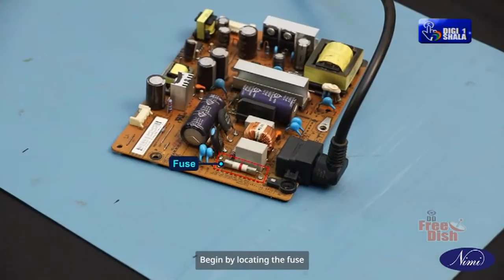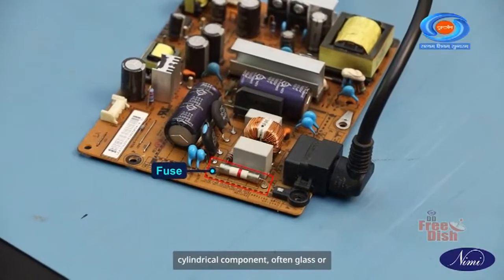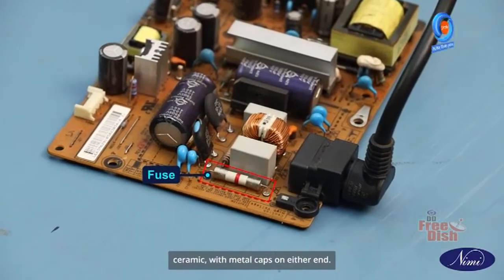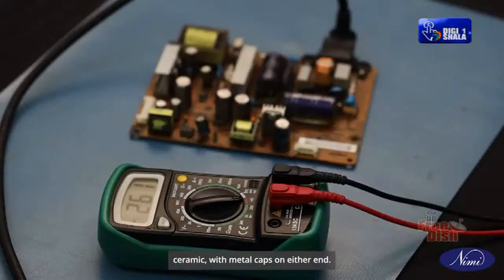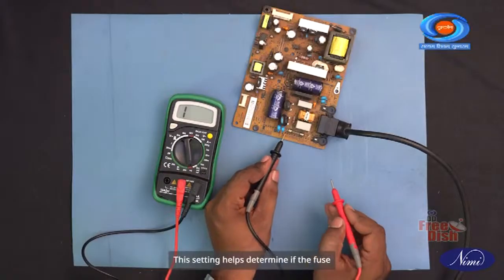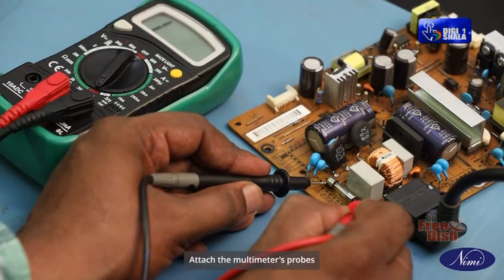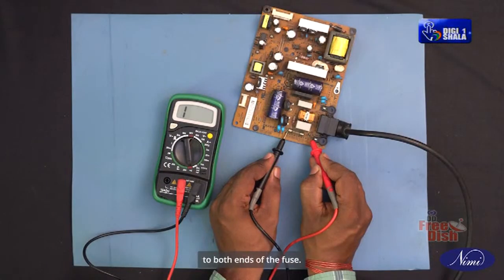Next, we will inspect the fuse. Begin by locating the fuse on the power supply board. It is typically a small cylindrical component, often glass or ceramic, with metal caps on either end. To test the fuse, we will use a multimeter set to continuity mode. This setting helps determine if the fuse has a continuous electrical path. Attach the multimeter's probes to both ends of the fuse.